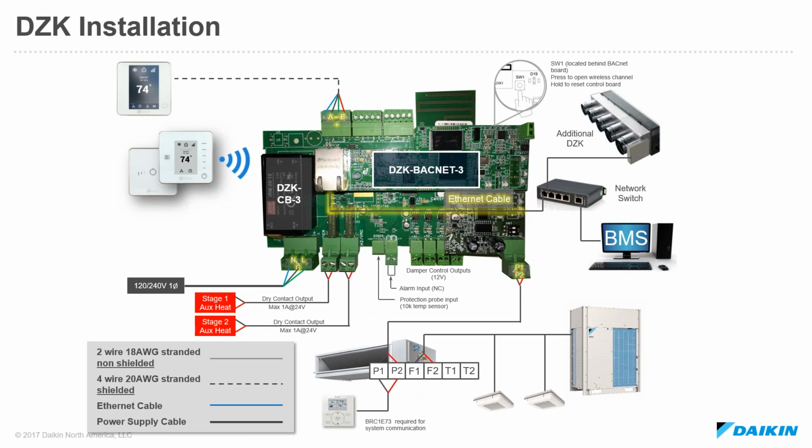The top side of the screen here, you'll see the wired thermostat, where this wires back to the appropriate wiring harness landing point for wired thermostats. You'll see up to 3 different landing points for wired thermostats. So if you have 6 different wired thermostats, you end up having to double up and wire 2 different wired thermostats to each of these wiring harnesses.